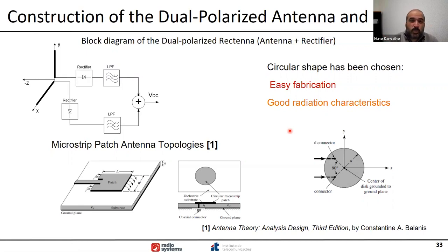But the problem is that if you want to do this for IoT, you don't really know if your sensor is going to be aligned with your antenna or completely misaligned with your antenna. So what we propose in that situation is, instead of using circular polarization, use dual polarized antennas, and instead of having one RF to DC converter, have two RF to DC converters that create two DC collectors, and this way you can maximize the energy at your receiver all the time.